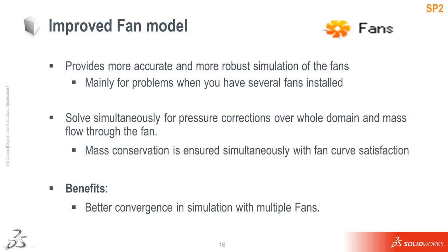A fan is a type of flow boundary condition considered as an ideal device creating a volume or mass flow rate depending on the difference between inlet and outlet pressures averaged over the selected phase. SolidWorks Flow Simulation 2012 SP2 offers an improved fan model for a more accurate and more robust simulation of the fans, mainly for simulation when you have several fans installed.